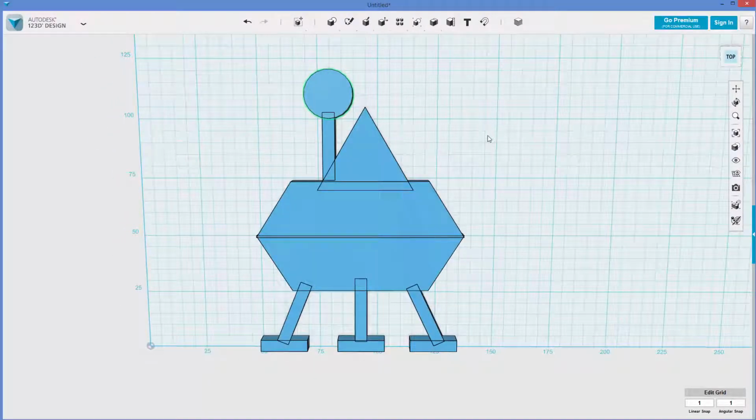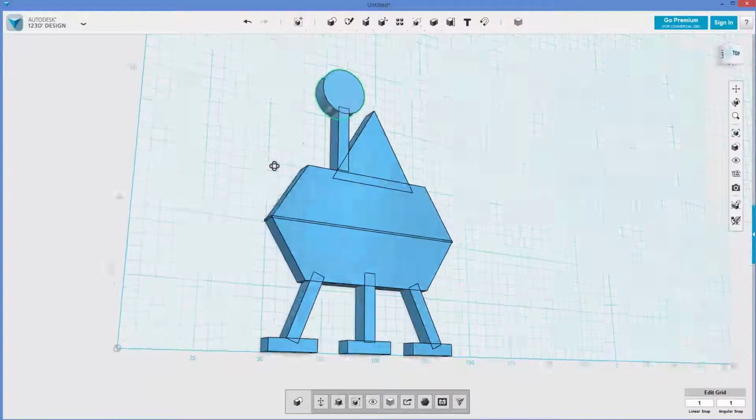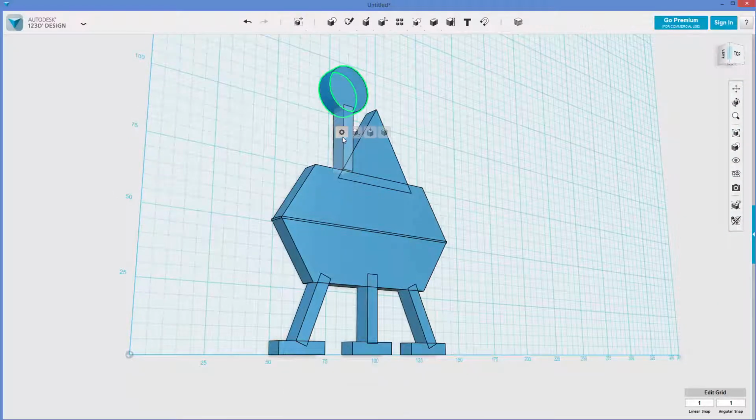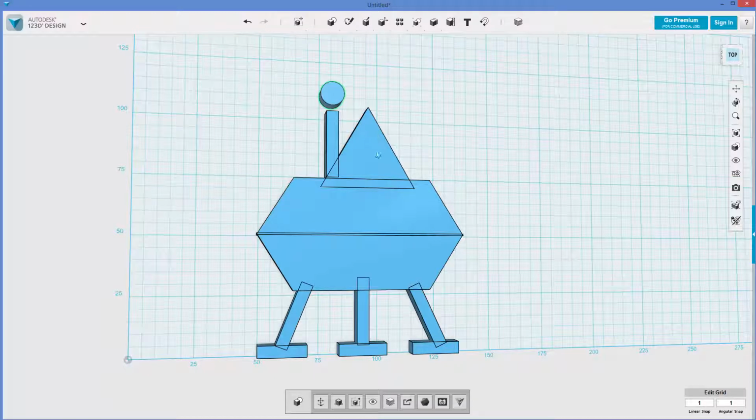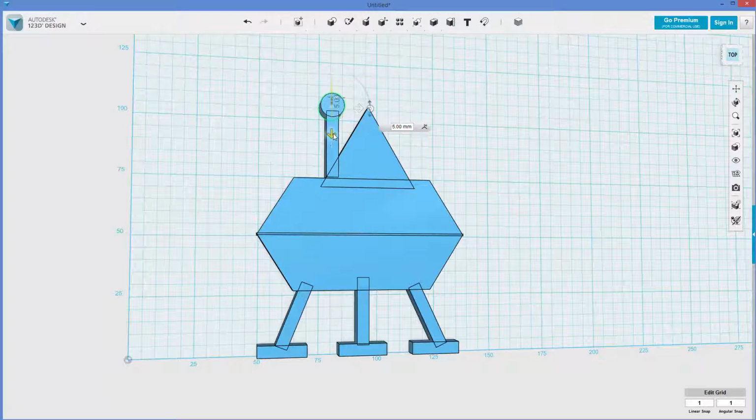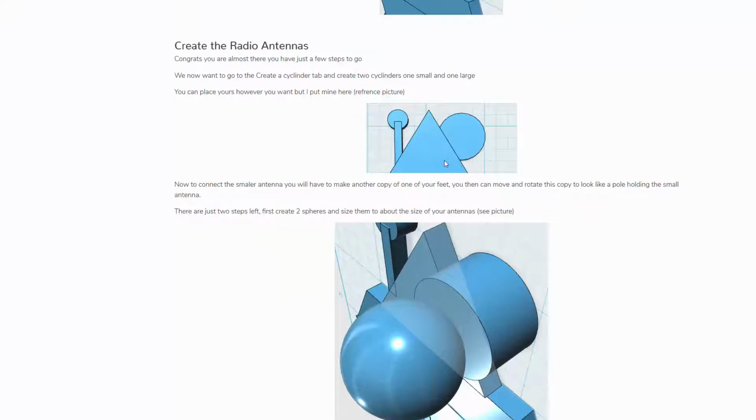All right, and now I'm going to actually just do a normal scale because, well, tell you what, I'll do a press pull. There's more than one way to do this. Press pull, grab this face, drag it in, and now I want to move this. If you hover, you'll see it's Control T to move. Control T. Now I'm moving this down. There's that antenna. And then the other was a bigger dish.